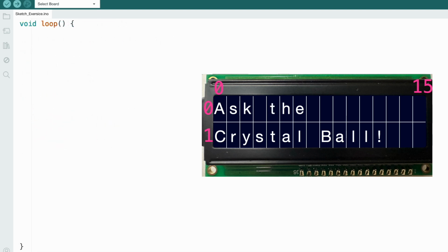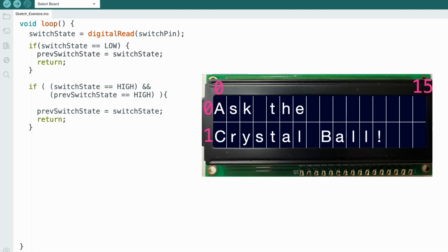And when we're looking at the loop, there's really just a few things here that are maybe a little bit outside of what we've already talked about. But we have the digital input, right? The digital read. We've seen this plenty of times. This is what reads in when the button is pressed, or if you're using that tilt sensor, whenever it tells you the board tilted. But like I said, I'm changing the hardware to press a button. And the first thing that I'm going to do is take a look at my current state. What this is going to allow me to do is not print out new messages if they're not holding down the button.